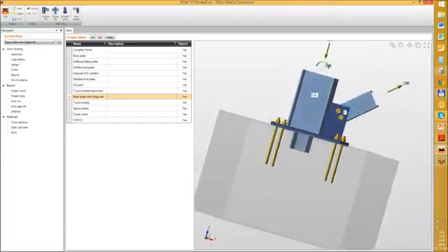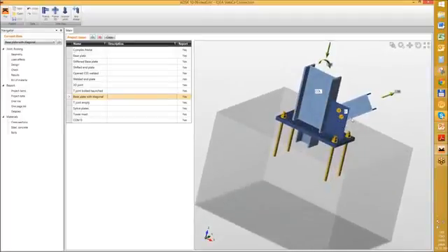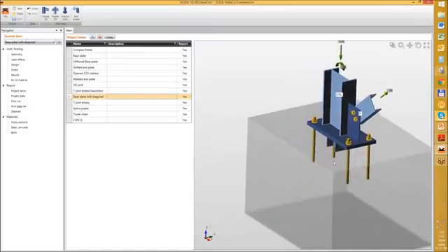It is quite important because if you calculate it like that, the situation can be worse, but it can be also better. For instance, here this gusset plate in fact works like a stiffener of the base plate. So if we connect this one more member to the connection, in fact we can help the connection, and we can make a more efficient design.